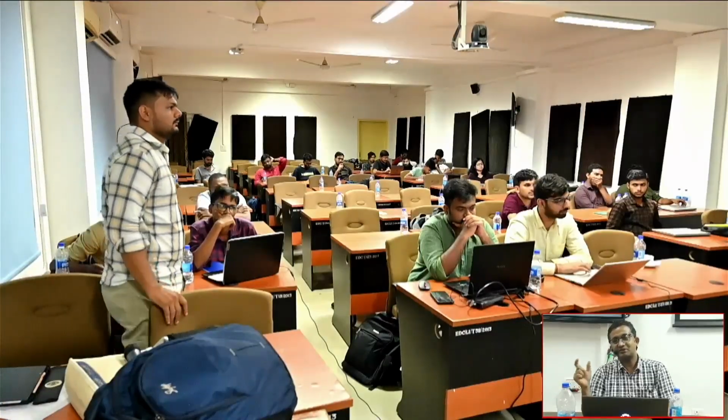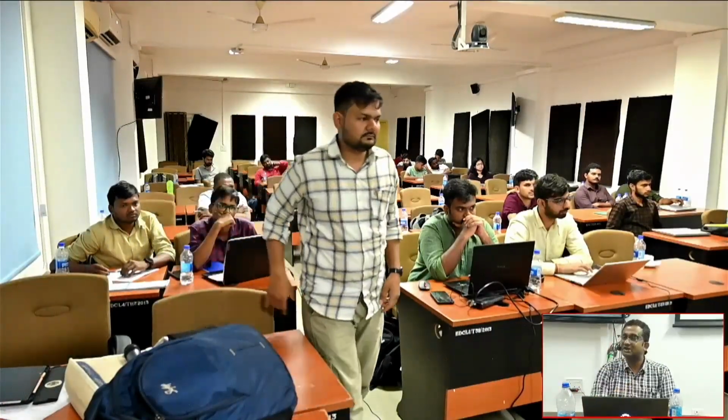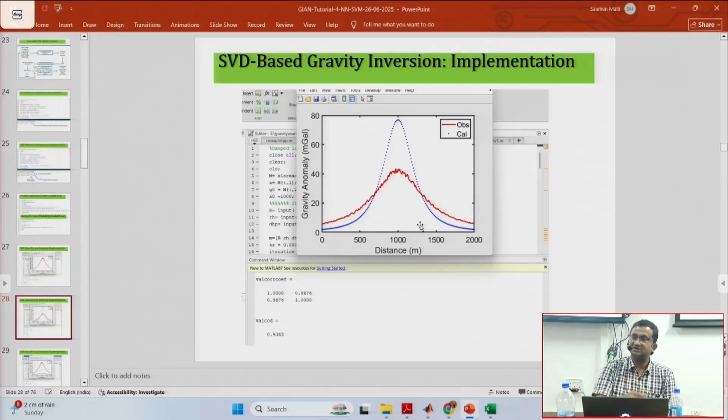So this type of uncertainty can be removed. Once the depth parameter is sure, the other parameter can follow. The right hand side is known, the left hand side is the product of both. So if one parameter you can access directly from sampling inside the earth, then the other parameter can be better controlled, and one can resolve this equivalence problem.